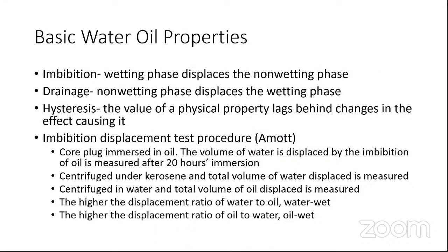Other basic water oil properties: you have imbibition, where the wetting phase displaces the non-wetting phase. You have drainage, where the non-wetting phase displaces the wetting phase. Then you have hysteresis, which is the value of a physical property that lags behind changes in the effects causing it. Imbibition displacement test, there's a procedure on it, and that's written by Amit.